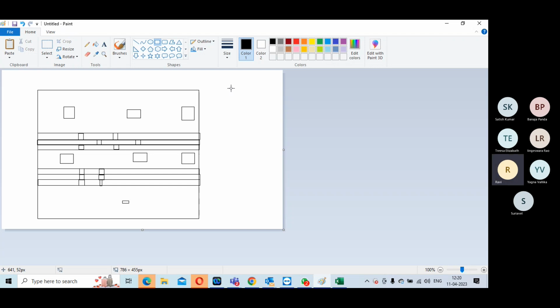Understand? They will confuse you like this: should the isolation cell be placed in the off domain or on domain logic? It will always be in the shut off domain block only. It won't be in the always on domain block. But it has to be connected to always on domain power. It should sit inside the block which is supposed to be shut off, because even if it's shut off, this cell should be on. It should only be on the nets which are going from off domain to on domain.